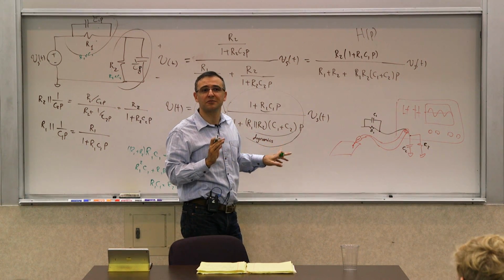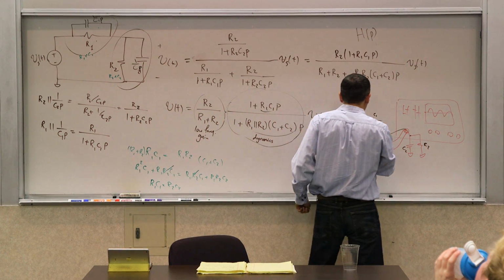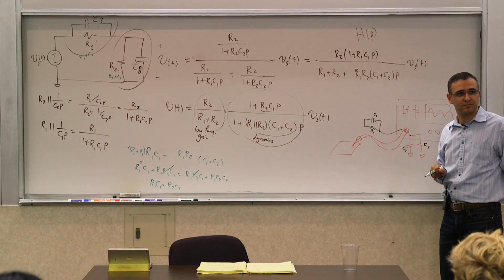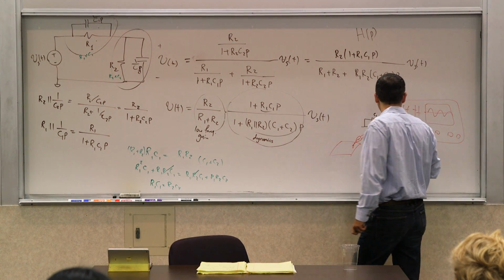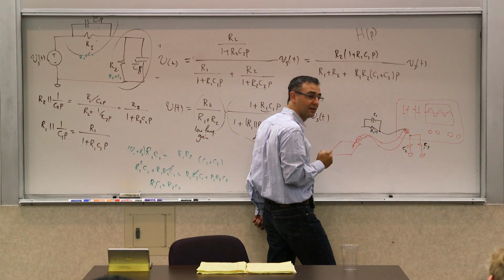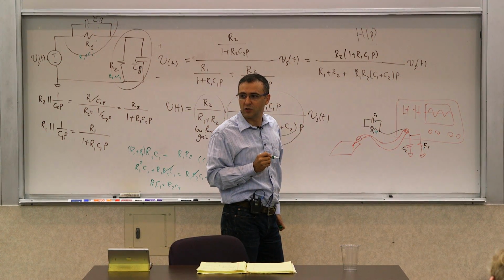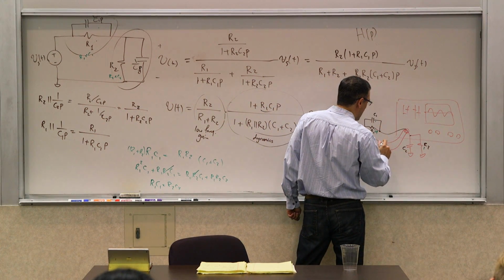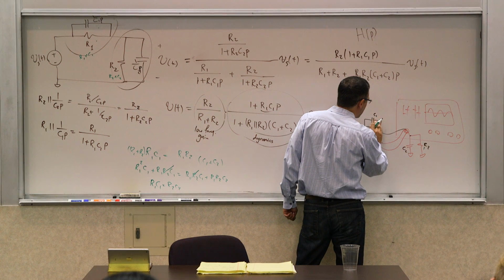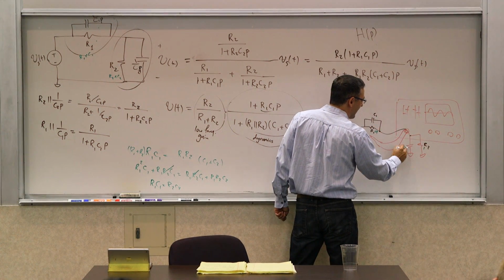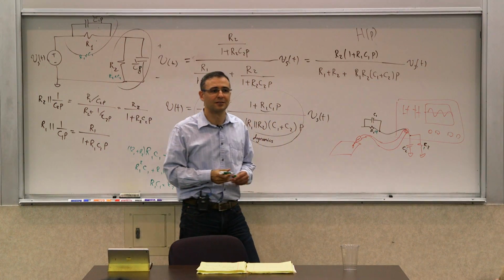So it acts like a resistive divider. So what you do, if you make this product the same as that product, and the way they do it, they make this 9 resistor, and they make this 1. So 9 to 1. Now 9 something, 1 something. The ratio is 1 to 1. Now what you can do by putting the right capacitor here, you can actually make this go away, make the effect of this capacitor disappear.